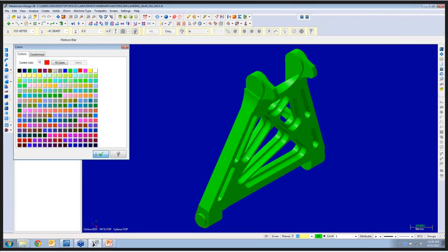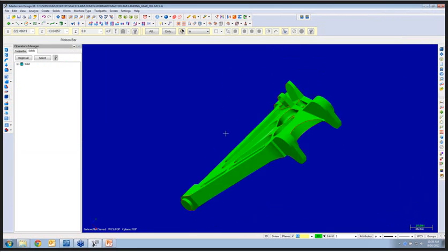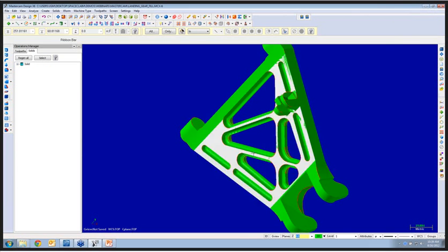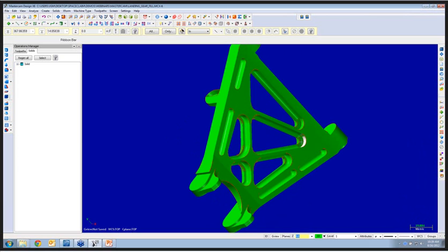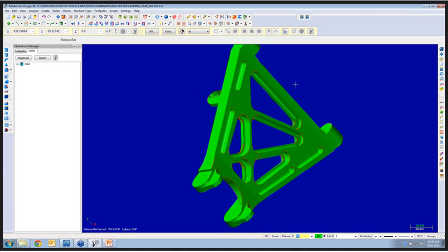All these red lines right here are gaps in the faces and edges, and you'll see there's a face missing right here. This face is missing, and all these red lines around here are faces that are not actually watertight. They're not mated correctly. So I'm going to go ahead and export this out of MasterCam using a quick export button, export to SpaceClaim, and send it over to you, John, into SpaceClaim, and you can work with it. Great.